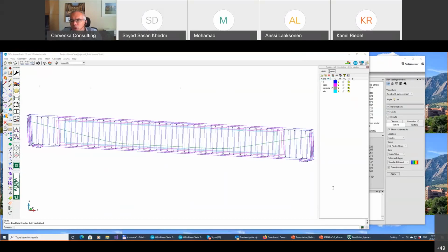So there is a special way: when you apply this loading, you also give it a function of how step relates to time. So of course you have to define some proper history, a loading history, but the answer is it is done within a static analysis. So there is no need to make another transport analysis,